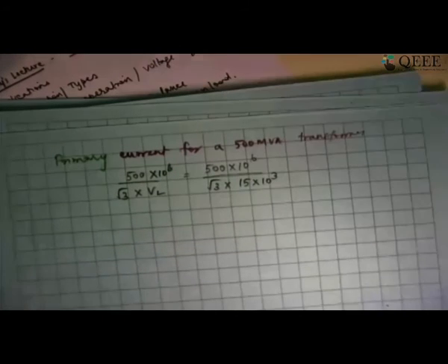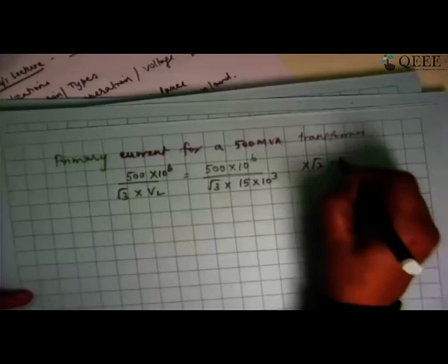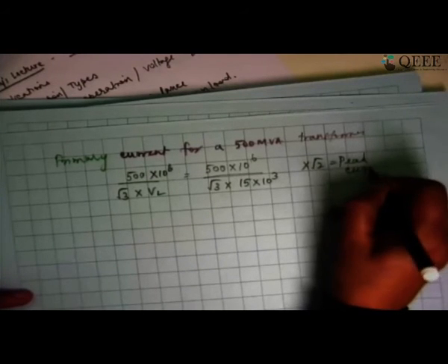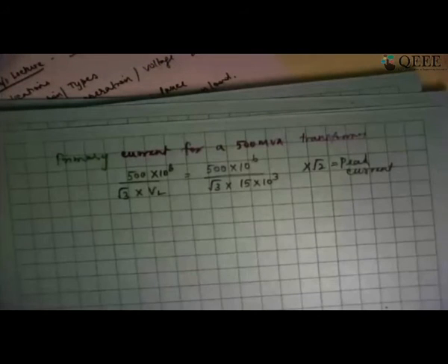So you can calculate how much is the current, but we have to rate the conductors always for the peak current. So I have to multiply this by root 2 for the peak current. So the conductor sizes will be enormously high, because, compared to copper, it is all copper, agreed, but generally, even for carrying 30 amperes of current, we need at least 1 centimeter diameter. So you can imagine, if I have to carry so much current, then correspondingly the thickness increases tremendously. So it depends heavily upon the rating of the transformer and what is the generation voltage.